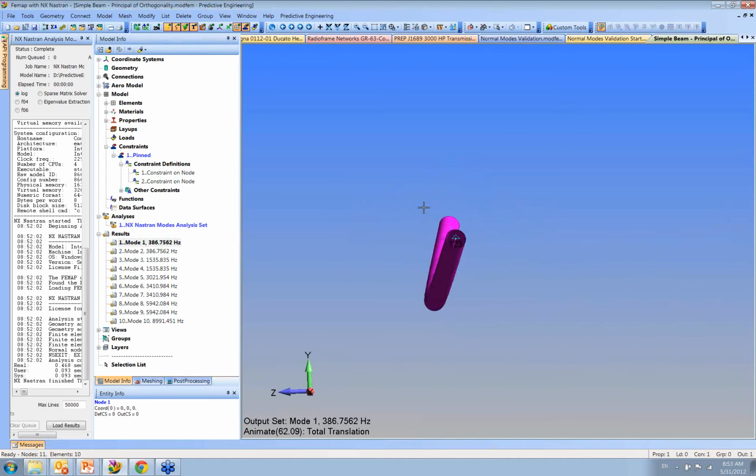Almost at right angles. A little bit tricky, but what it's doing is that in a beam structure like this, if it wasn't just showing these two modes, you could have a near infinite number of modes in 360 degrees, because that's really how it can vibrate. It can vibrate in any sort of plane of that rotation.